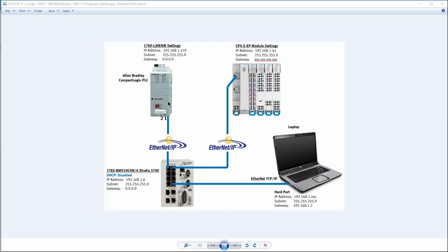and sometimes you can have some really low-end Rockwell PLCs that only offer 4 connections. So the I/O Diagnostics Interface occupies the process data. Therefore we only need the one connection to here, and we can still get advanced diagnostics without having another connection, similar to using the explicit messaging. Okay? Alright, so let's move on to the next step here, the Festo website.